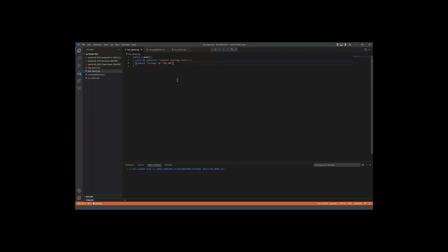So what I'm going to do is after C1, we've determined that I need to put in the command D. And then we need to put in 2 more commands. Instead of giving it coordinates, I'm going to type in 100 for both of those. And the only last one is the final coordinates for what direction it's in. But if I type in the original coordinates again, it'll just place it so that the bottom left of the square is on my cursor, where my cursor is.